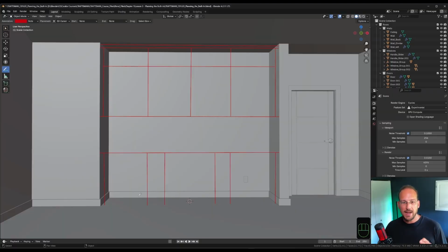What does that mean for us now when we have to take the measurements? Well, as I said earlier, we have to keep in mind that walls are never perfectly straight. There might be bumps in there, they might be out of plumb. So we want to take at least 2 measurements along the height. So on the base cabinets, we want to take at least the length from here to here and the same along the top.